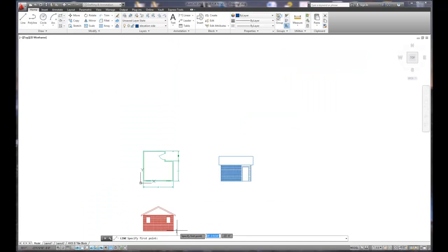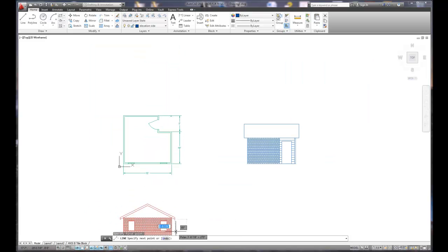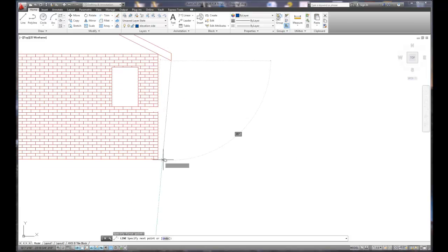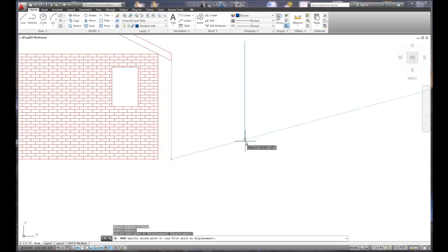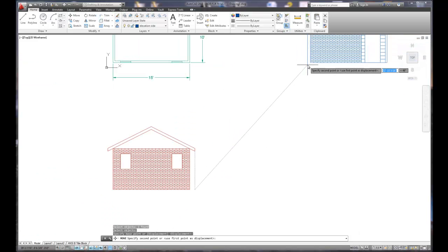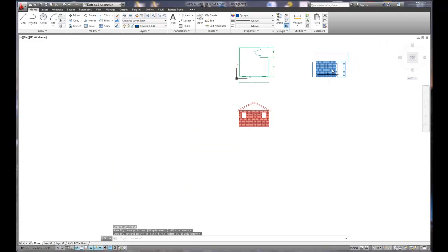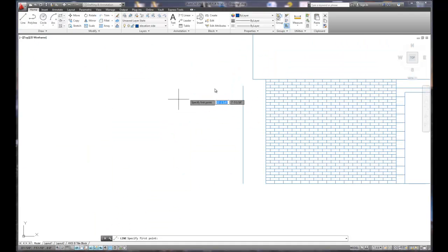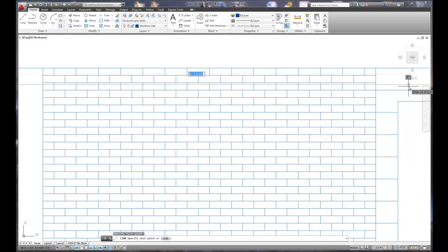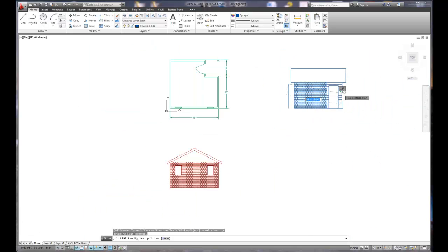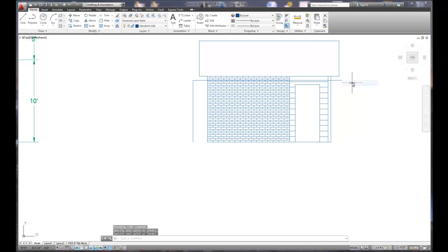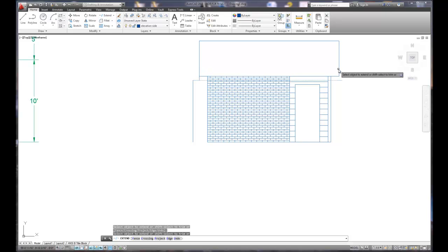So line, and then I can move the line. Okay, so the height of that line now is the new fascia board location. So theoretically, boy, I hate when that happens. So I'm going to use the extend command to extend the 2 lines to it. Use the fillet tool to clean up the edges.